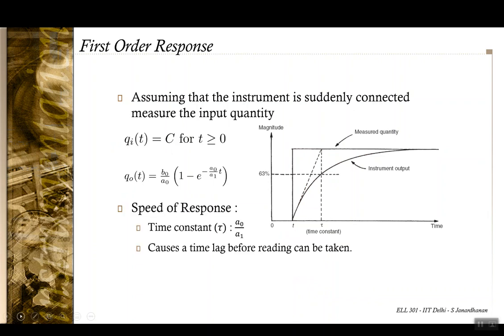As I said earlier, in this case the time constant is a0 by a1. Sorry, the time constant is not a0 by a1, it should be a1 by a0 in this case. And this time constant would cause a lag in the reading. So it causes a time lag before the reading can actually be taken.